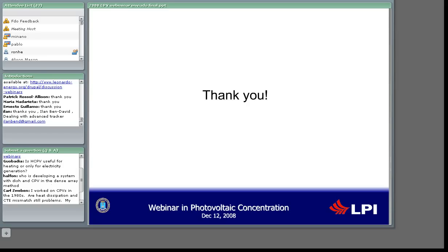Thank you. Yes, heat dissipation is still a big issue of CPV systems, because the temperature decreases the cell efficiency. The biggest problem, the bottleneck of the heat flow, used to be the contact between the cell and the first heat spreader, and this contact has to be very good from the thermal point of view, but at the same time, in this region, depending on the configuration, there are problems of electrical isolation.